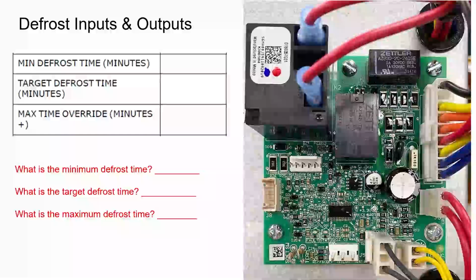Okay. Now, we do have a max amount of time for defrost. So we will not allow a system to stay in defrost more than about 10 to 12 minutes, depending on the version of the board.